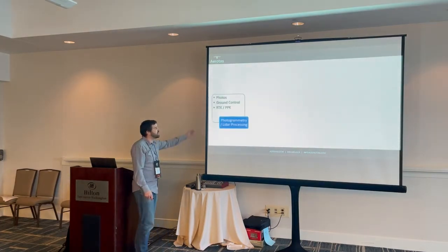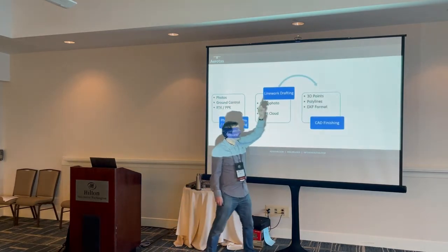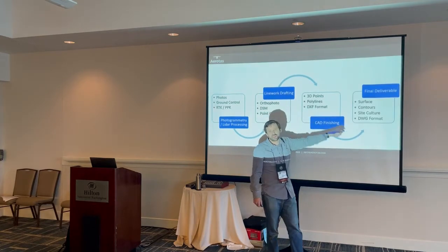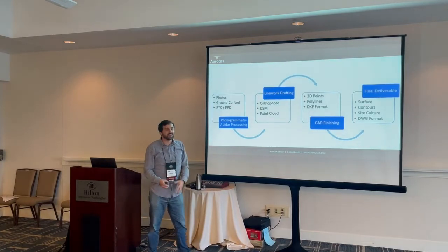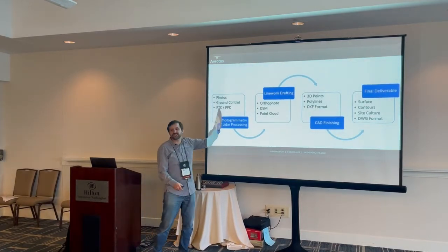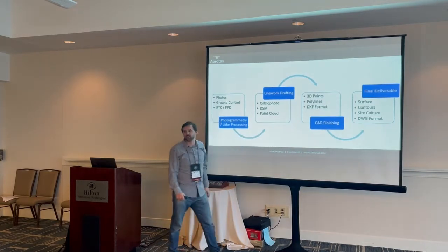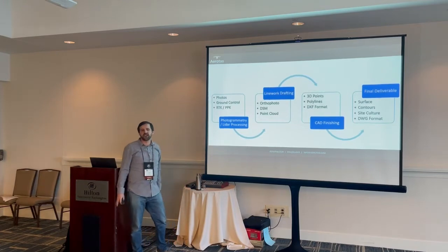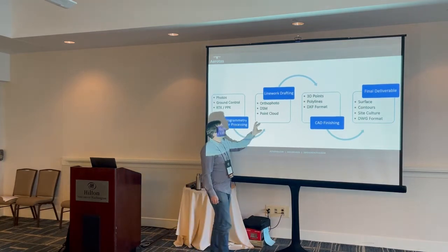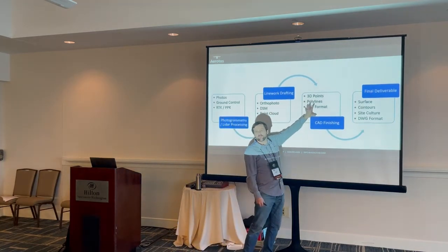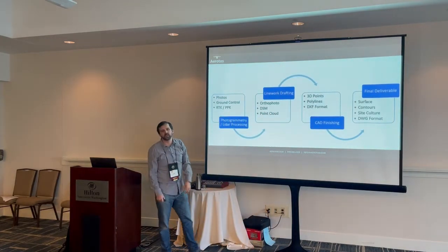So again, I think I showed you this: LiDAR processing, rich models, linework drafting, clean, simple data, CAD finishing into your final deliverable. This is a pretty important set of the workflow of how we actually get it. And the other thing that's important to us is having these clear distinctions, right? So once something is through this step, it's basically frozen, unless we discover some very unusual accuracy error, like if the client sent us wrong ground control point data. It's pretty much frozen. And then once we go through the linework drafting, we try to freeze it here, and only if we discover we missed something will we go back and draft some more data to bring it in and create a TIN model.